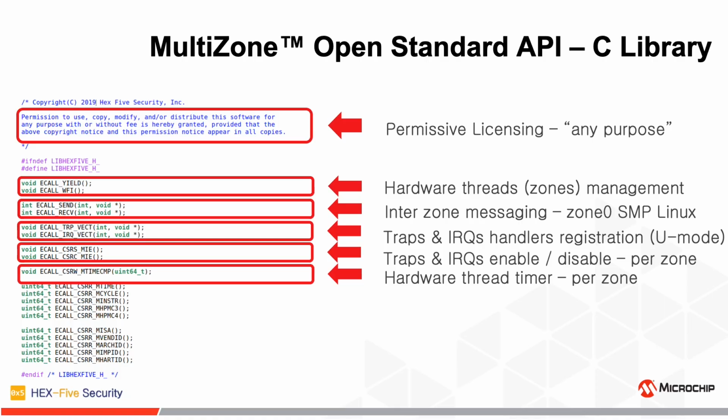Multizone provides soft timers, typically, let's say in this way. The RISC-V specifications include one real-time timer for the use of the operating system in the core. Now that's been delegated really to the platform level, meaning outside the core, that's fine, but still you have one. And so what if you should run 3 operating systems, each one in one zone, while Multizone provides soft timers. And this is the way you can run as many operating systems or applications that extend the required time in there.